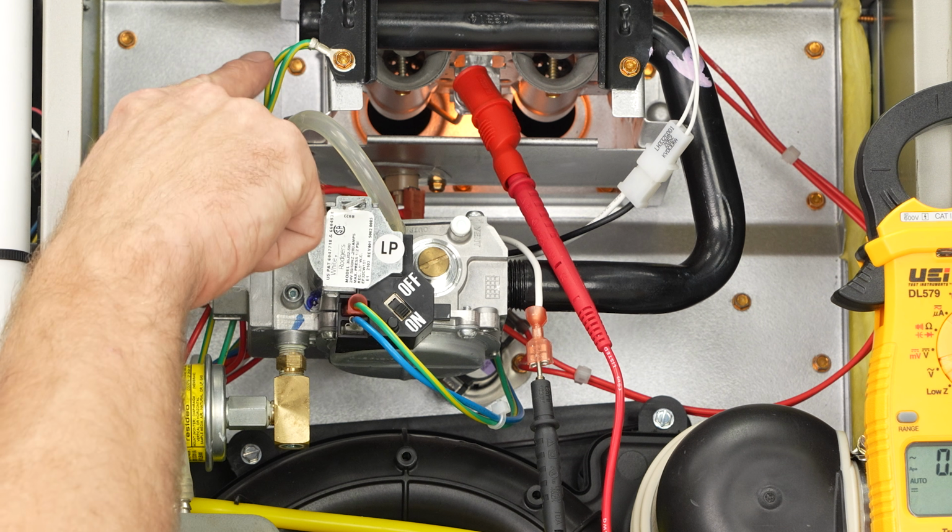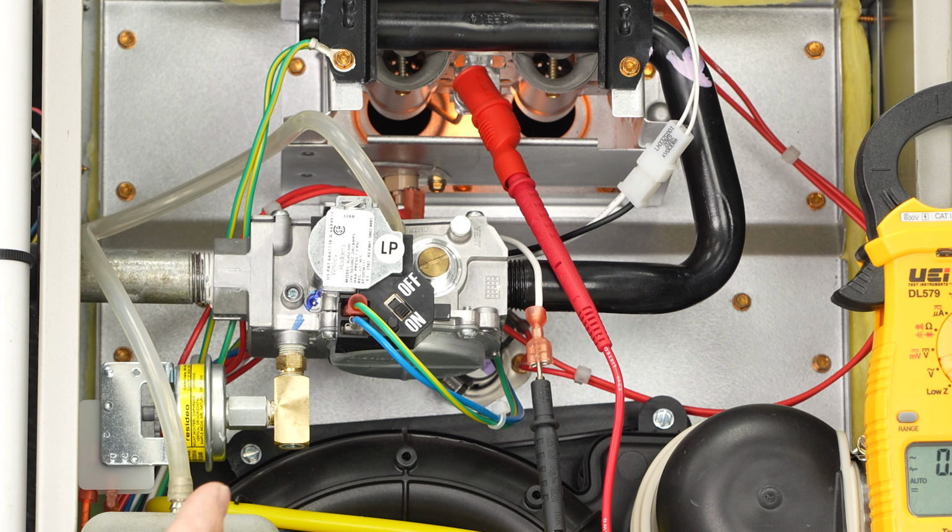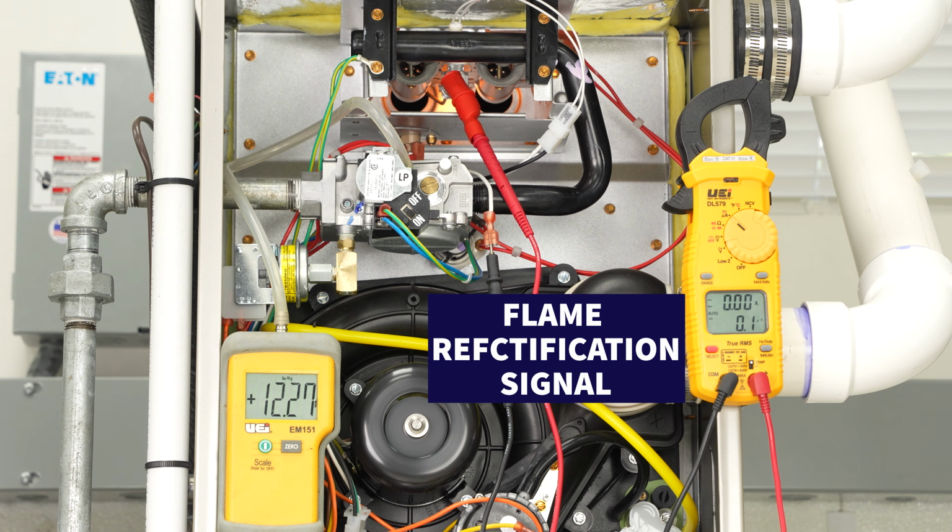Another thing could be, say, this ground wire. You could have a loose ground wire or a problem with your ground on the furnace, which could affect this right here, which is your flame rectification signal.